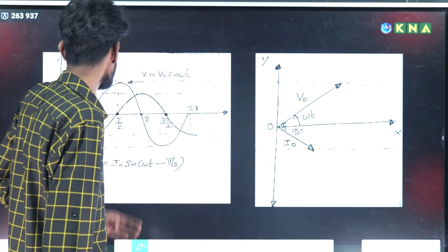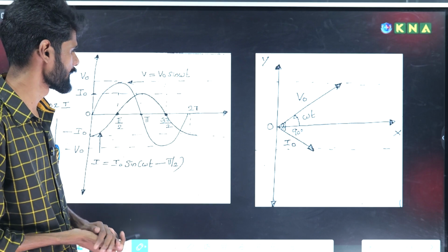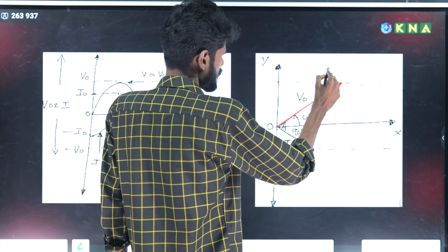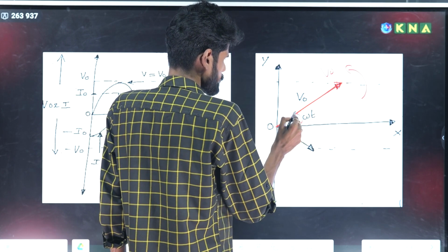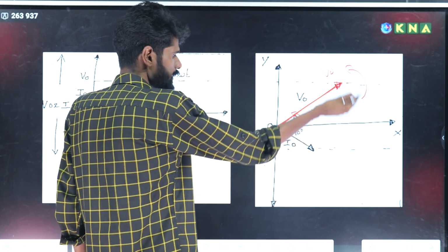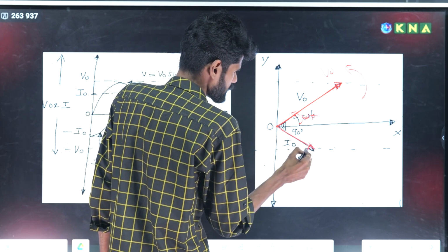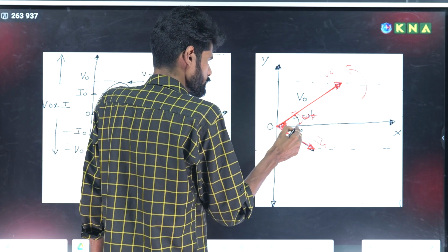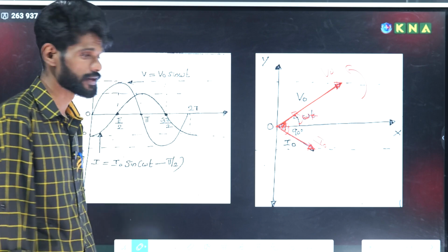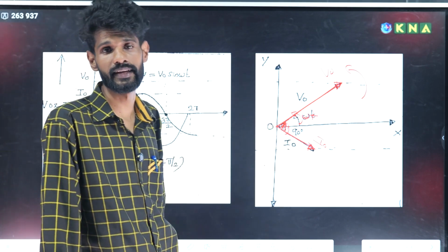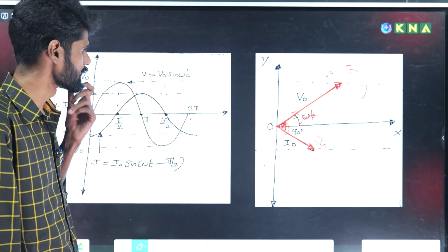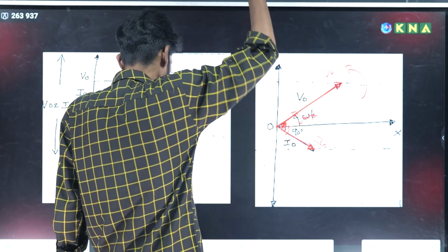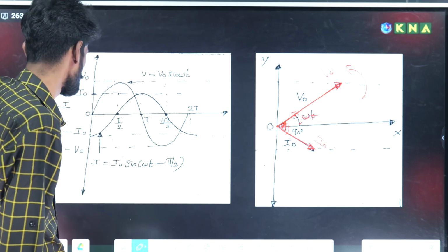And these are the voltage and current diagrams. So move on to the phasor diagram. You see the voltage phasor after t seconds, now it is omega t. So here voltage leads, and current has to come behind. The current phasor has a smaller amplitude. So here there is a phase difference between them of 90 degrees. So the voltage leads, that is, the current lags in a pure inductive circuit. In the phasor diagram, voltage comes first, current comes behind. The rotation of the phasor is in the anti-clockwise sense.